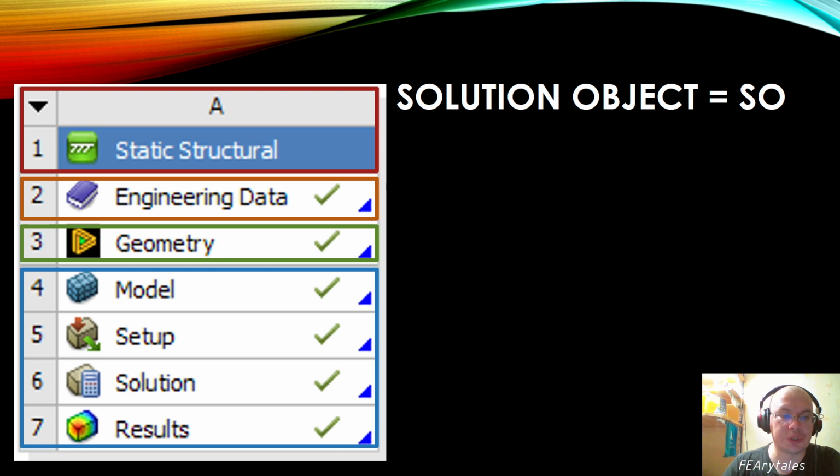For example, for CFX, the mesh model would be created with Ansys Mechanical. Setup will open the Ansys CFX preprocessor. Result will open the Ansys CFX postprocessor. And solution will open the Ansys CFX solver.